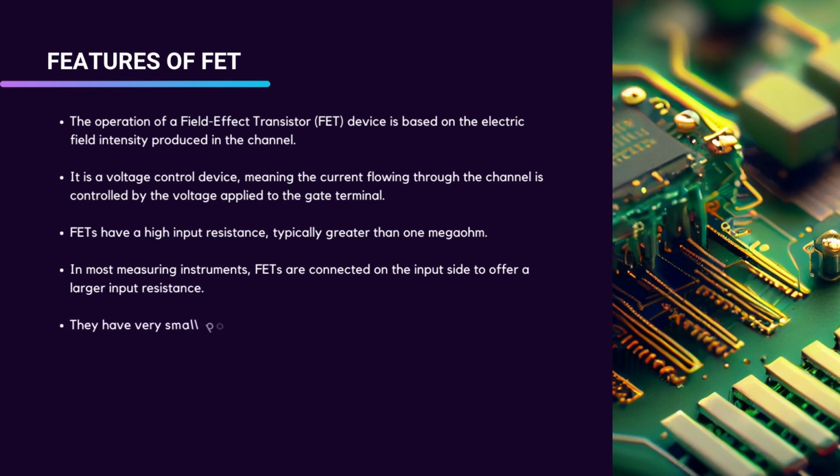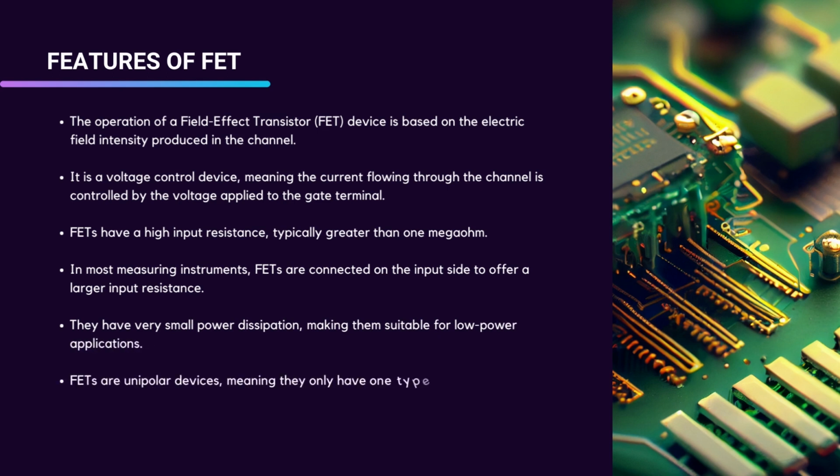The input impedance plays a very major role in electronic devices. So, the characteristics of the FETs, that they have high input impedance, make a very good choice in the semiconductor industry. In most measuring instruments, FETs are connected to the input side to offer large input impedance. As I told you, they have high input impedance. So, FETs are connected at the input side of the device, so they provide large input resistance.